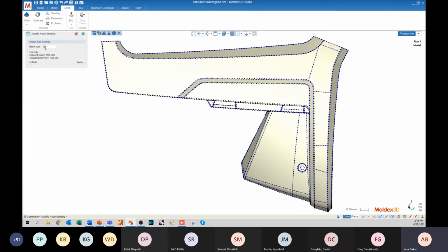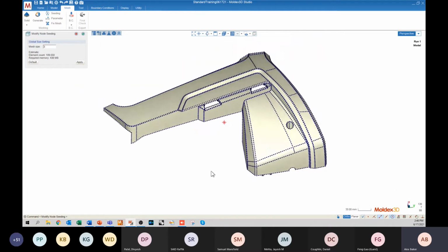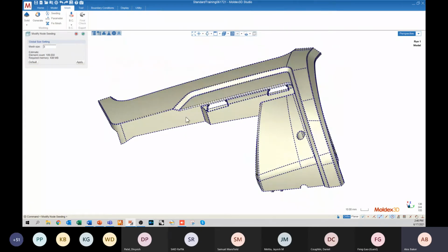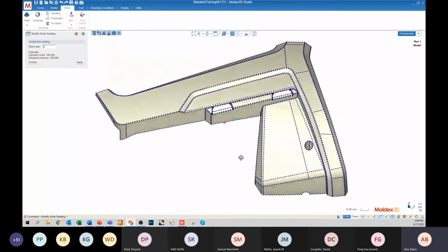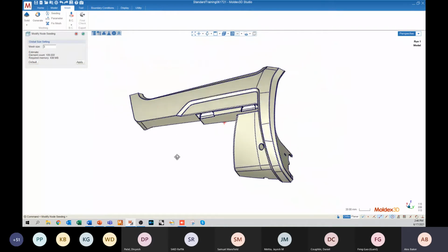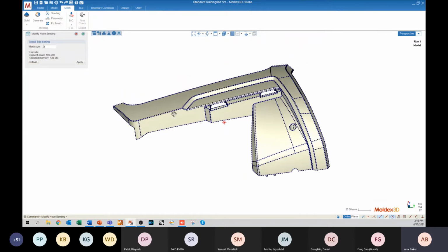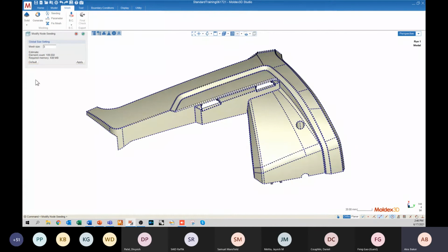And you can actually see that this mesh size is pretty close to where we started. Remember, our default was 3.197, and you'll find that a majority of the time, the Moldex3D default for more complicated parts is actually going to be quite accurate to the Goldilocks method. We've done this on purpose, and funnily enough, the more complex your geometry gets, the more accurate the default is. And the reason for that is because the more feature lines this function has to go off of, the more information we have to create a good average and to recommend a good default mesh size setting.